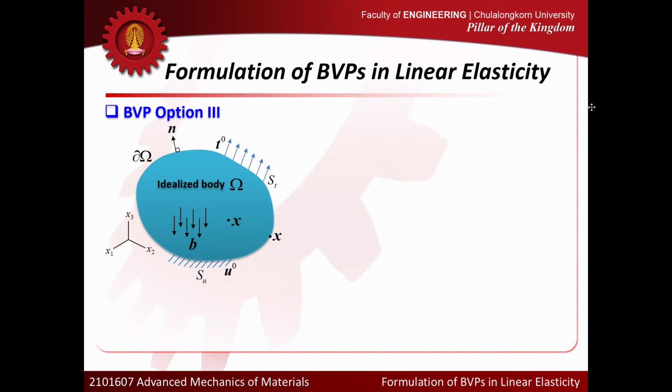That was for the case that the material is a general anisotropic material. Here I try to specialize to the isotropic case. You know that if the material is homogeneous and isotropic, we need only two constants to completely describe the behavior of the material. And we know that if the body is homogeneous, the material constants are not a function of position.